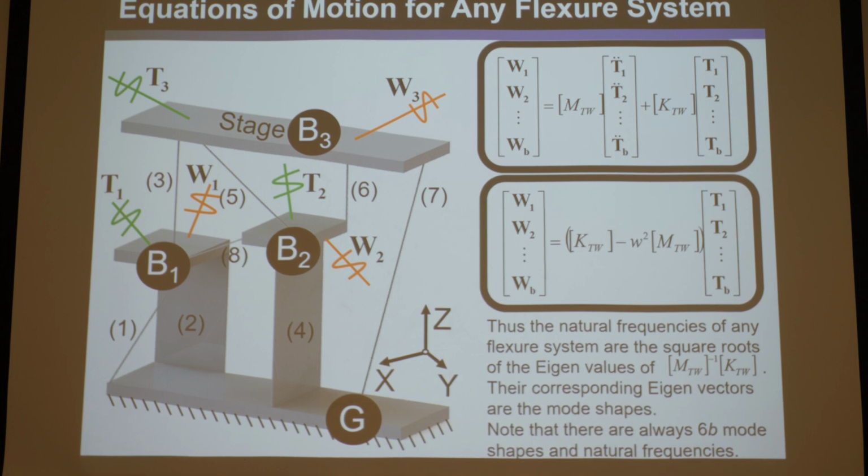I suppose I didn't teach you how to make the big stiffness matrix for interconnected systems, but anyway, you have a paper on it now, and now you can find natural frequencies and mode shapes, and you can load things quasi-statically or with some speed. If you wanted to consider the mass matrix, you can find how all the bodies in your system will move as a consequence of wrench loads and those kinds of things.